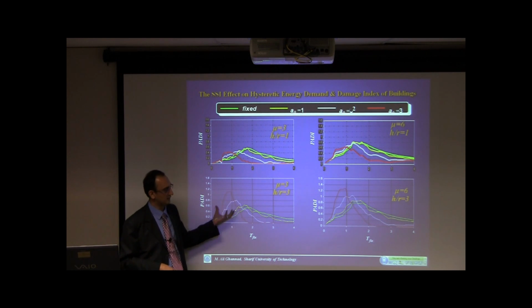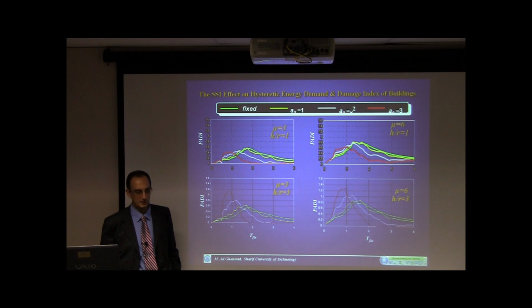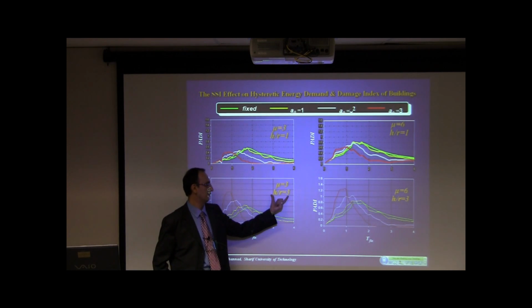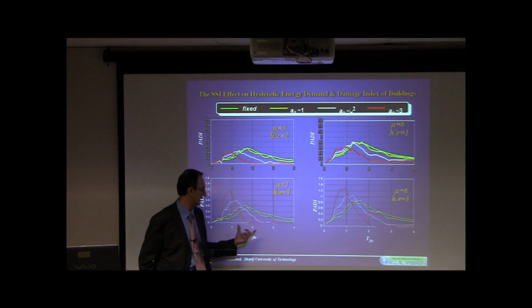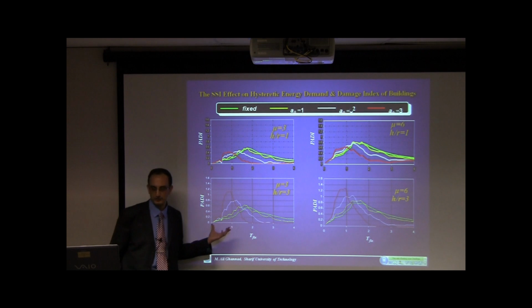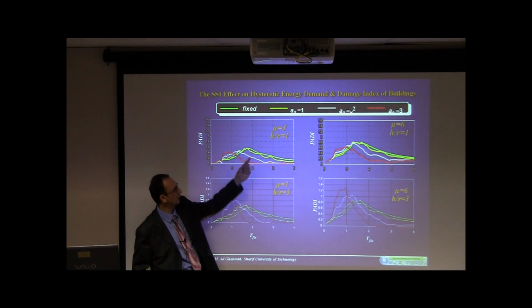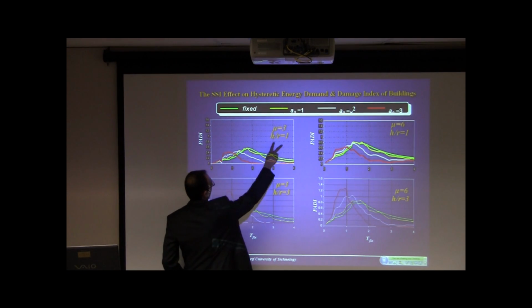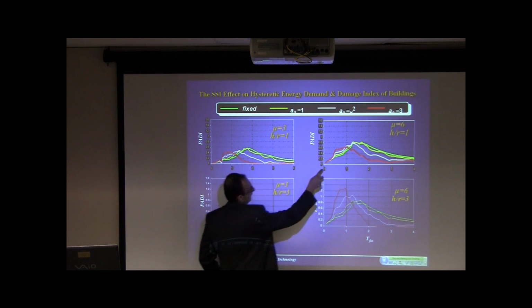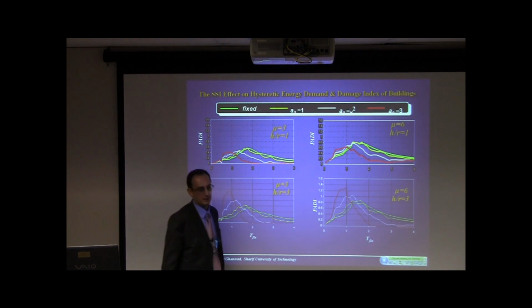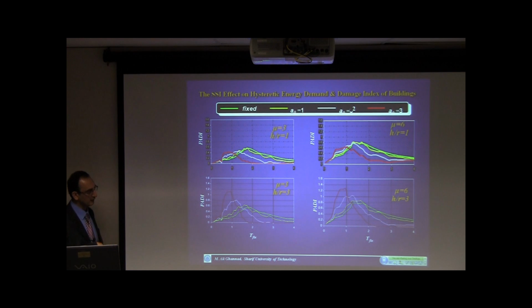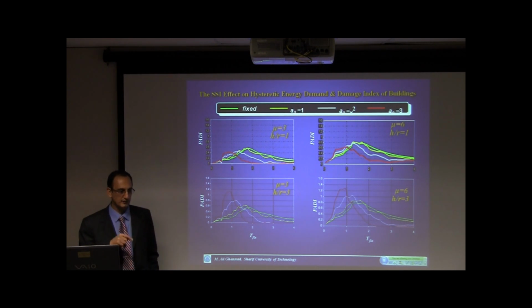But this result does not have any practical importance, maybe because structures with such slender ratios usually don't have such periods, of course. But with these aspect ratios, you can find periods in this range, and it happens that sometimes the structure located in the soil has more damage.